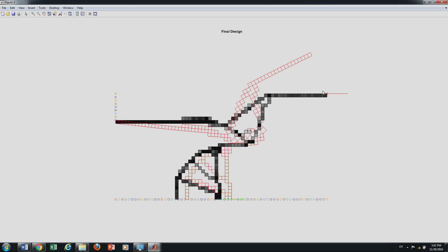So, you can make the formulation more and more difficult. I am not saying that I should put a roller here, so that it only moves in the x direction, that will change the boundary condition. Instead, I want a design where without any constraint here, it should move purely in the x direction. If you want that, then you should say that y displacement at that point is 0, and you have to put a constraint in the optimization and solve another nonlinear constraint. People have done that, but this program does not have that.